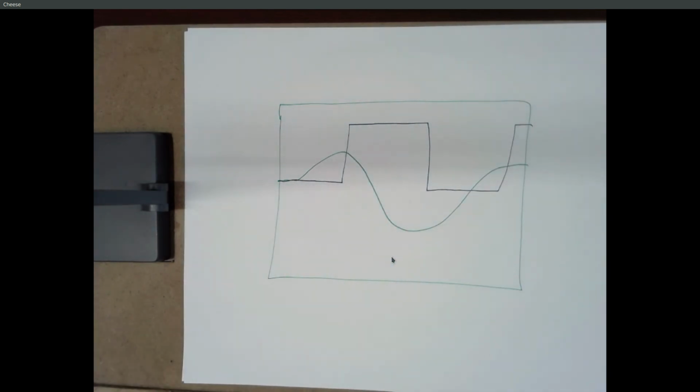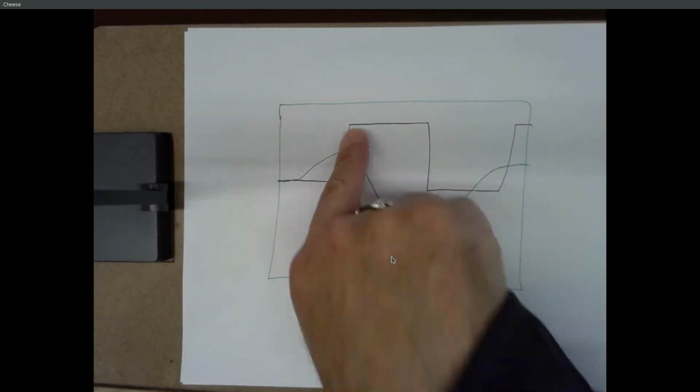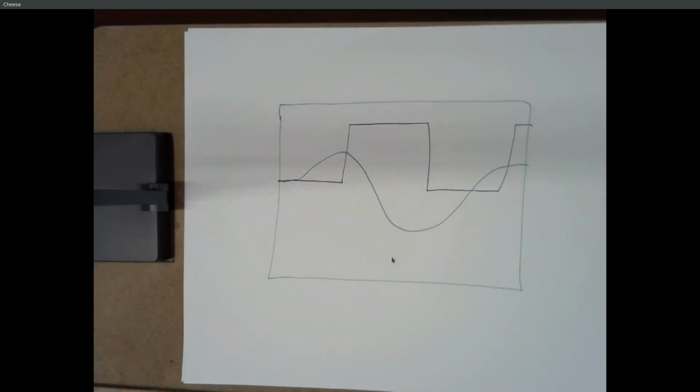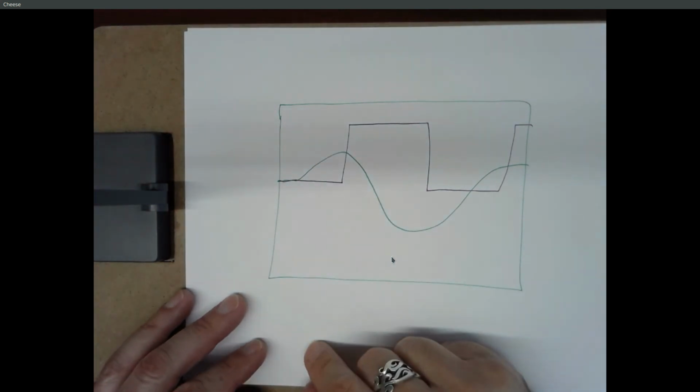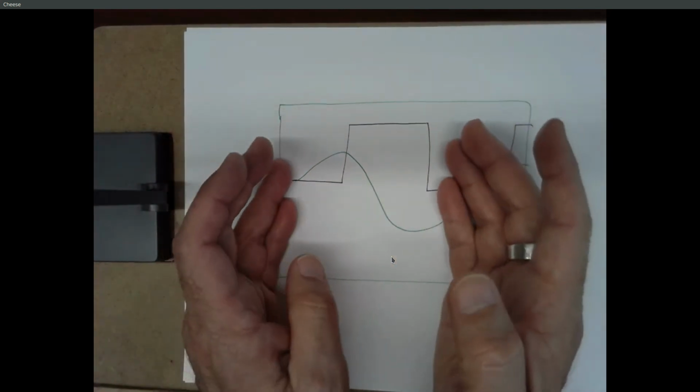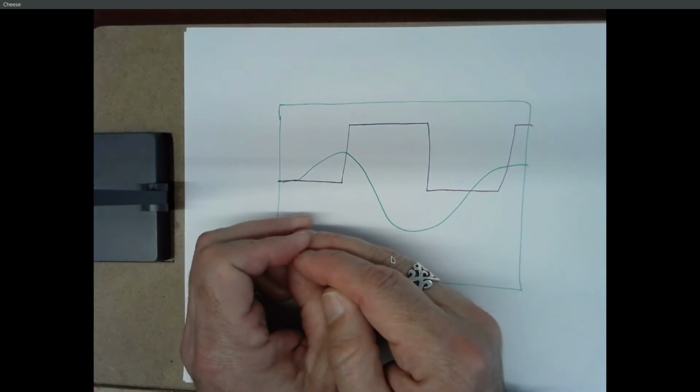Okay, that's effectively what happens inside an oscilloscope. Old days, it used to be an electron beam hitting a cathode ray tube, and now it's all done digitally. But that's the effect of it. So the thing giving the instructions on how far to raise your arm, that's the signal that you're trying to draw. So that might be what's coming from the function generator, and depending on the voltage going in, this beam gets raised or lowered a certain amount. And so in effect, you get an exact image of what your waveform looks like.